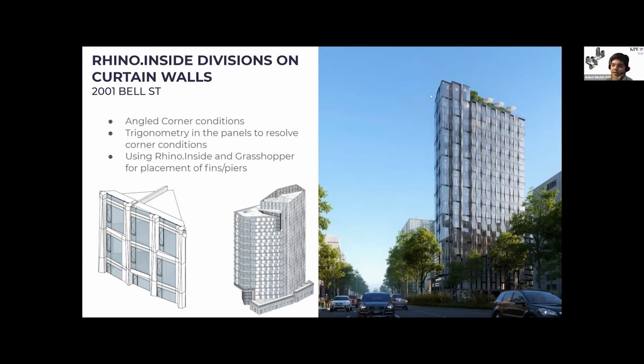And since the team was using Revit as the sole source of documentation and design tool, everything was put into Revit. So the curtain wall panels were normal loadable families, but they were placed, altered and changed. The types were changed using Rhino.Inside. Because there was a certain logic or pattern designed by the team, we were able to utilize that to alternate the panels inside of the facade, but also for the piers.